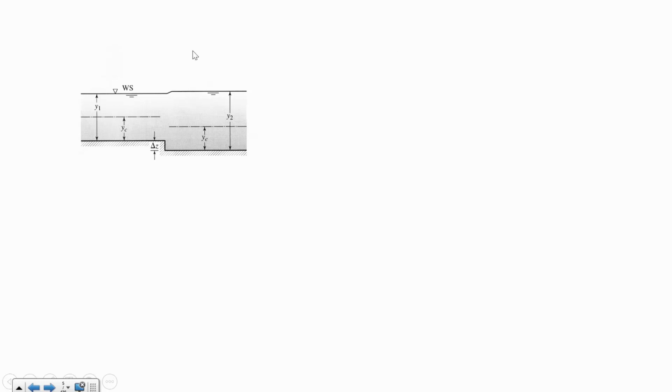Yeah, the depth is changing. There's a step downward. And if there's a step downward like this, then that means that the flow conditions are not constant with respect to position. Now, you'll notice that here in the sketch, what the author has done is put in a little imaginary dashed line to indicate what the critical depth should be for that channel.